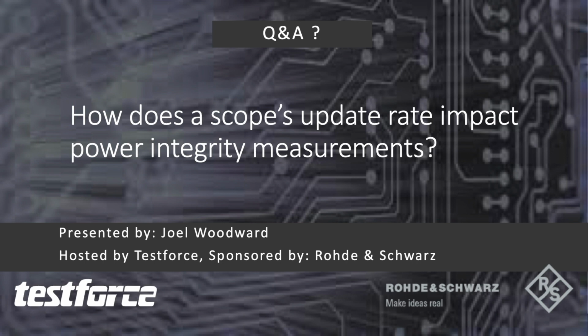Depending on your particular system that you're trying to measure, you might have a greater need to measure more real time to make sure that there's not any transient events that you're missing on the power rail. And for these cases, it's important to have a scope that has very fast update rate. Update rate is typically specified by scope manufacturers as a value when the scope is essentially after a default setup or a preset. And as you turn on additional memory, measurements, and other types of things, the update rate will slow down to some degree, depending on the scope's architecture. That degree might be greater or less.